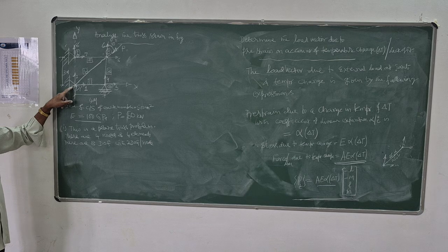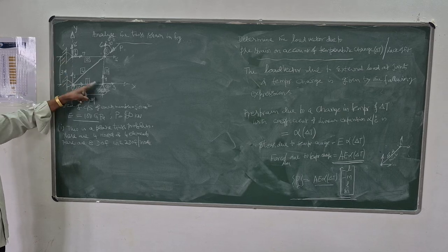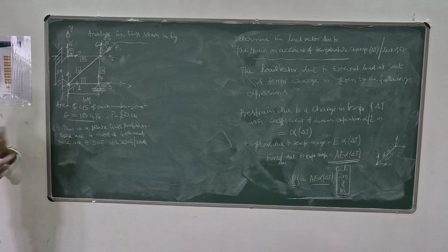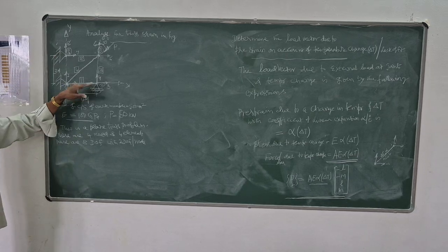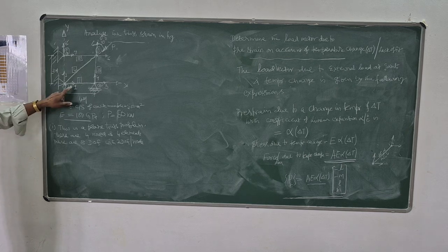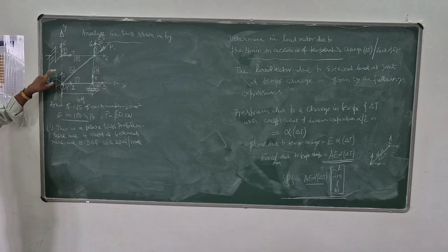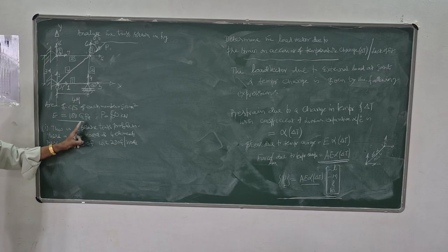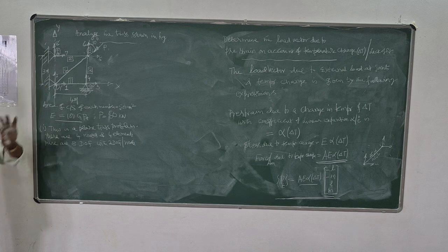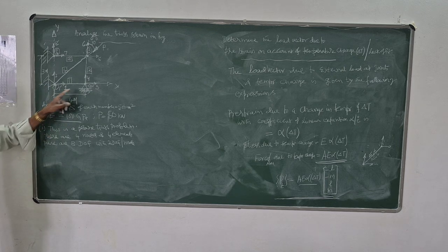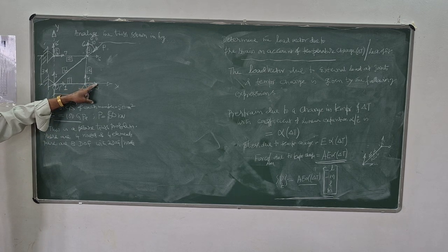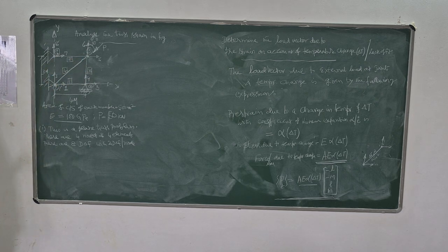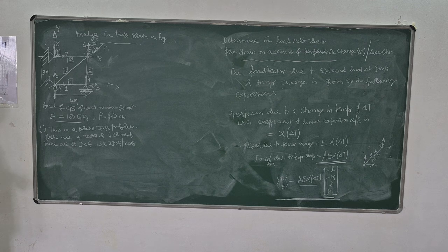Here you have a hinge support, here you have a hinge support, here you have a roller support. At a hinge support, no displacement is possible, both horizontal as well as vertical. So that is your Q1, Q2, likewise Q7, Q8, as well as Q4. They are 0. You only have to determine displacement along 3, 5, and 6. This you have to identify first.